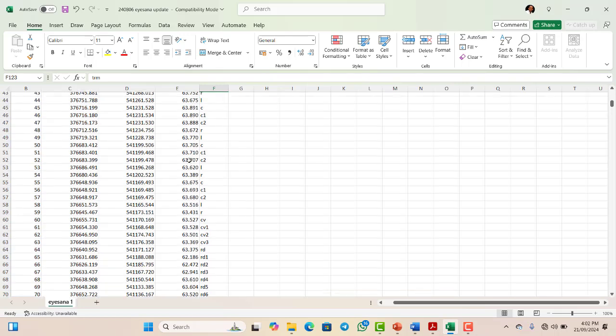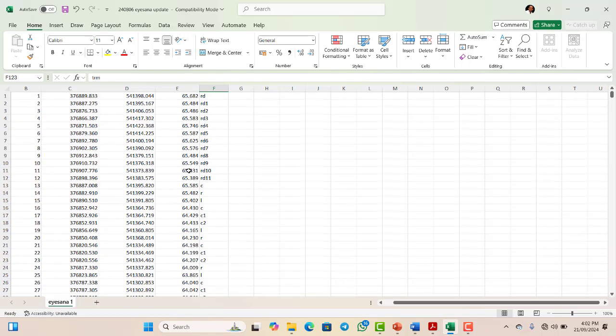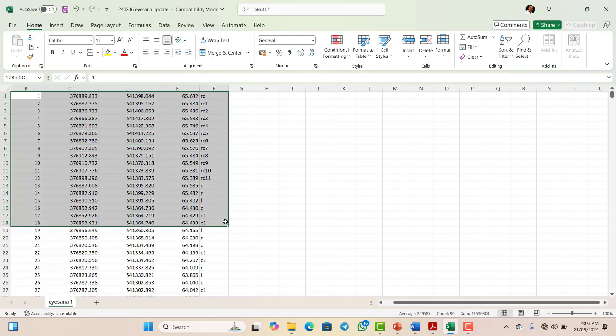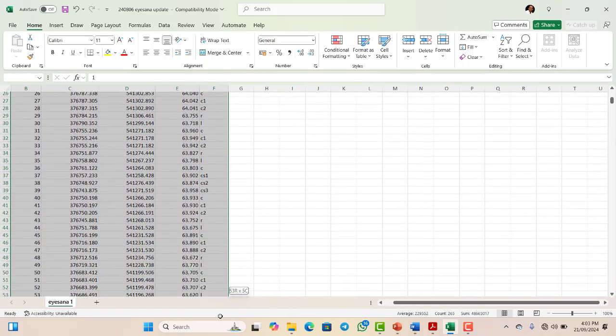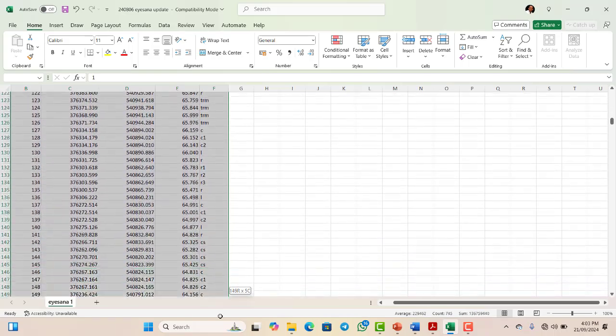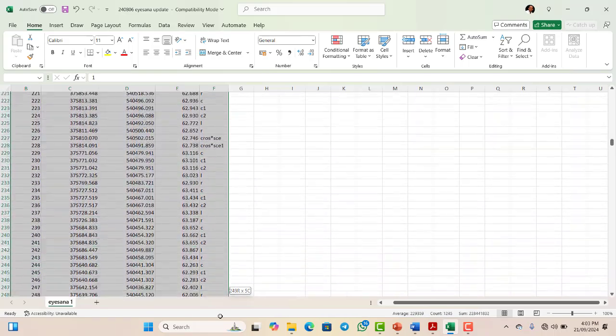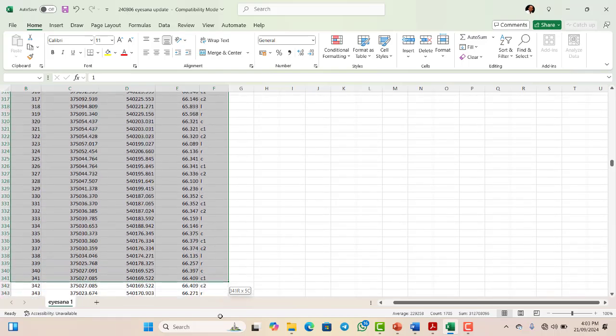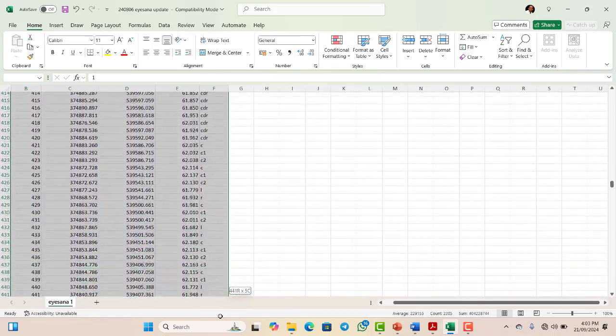I don't want to use this survey data directly. I want to change it to CSV format. So what do I do? What I'm going to do is that I will copy the whole of this information, and go to Notepad and paste it on the Notepad.